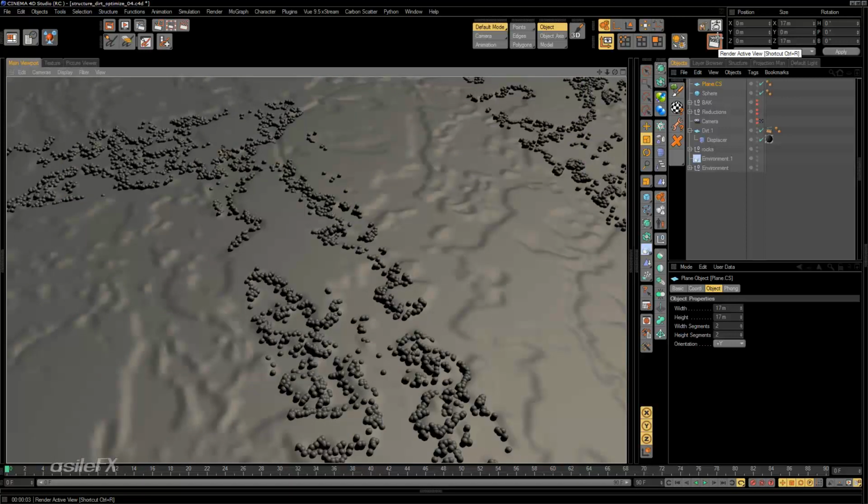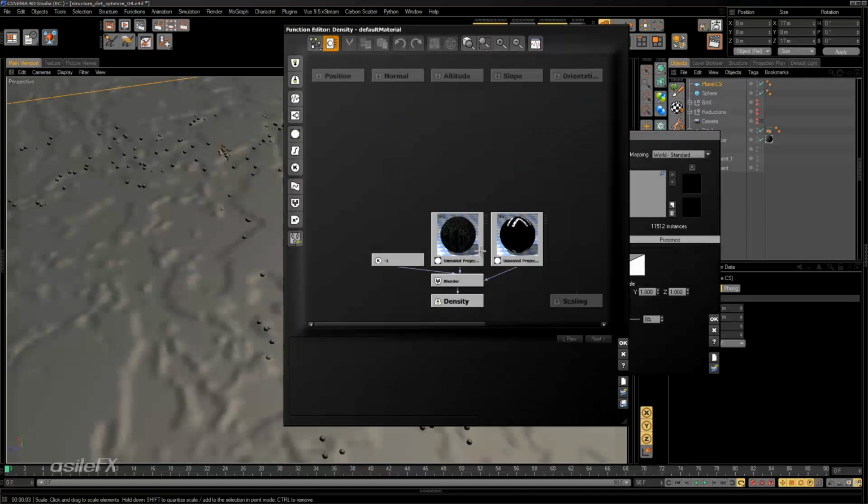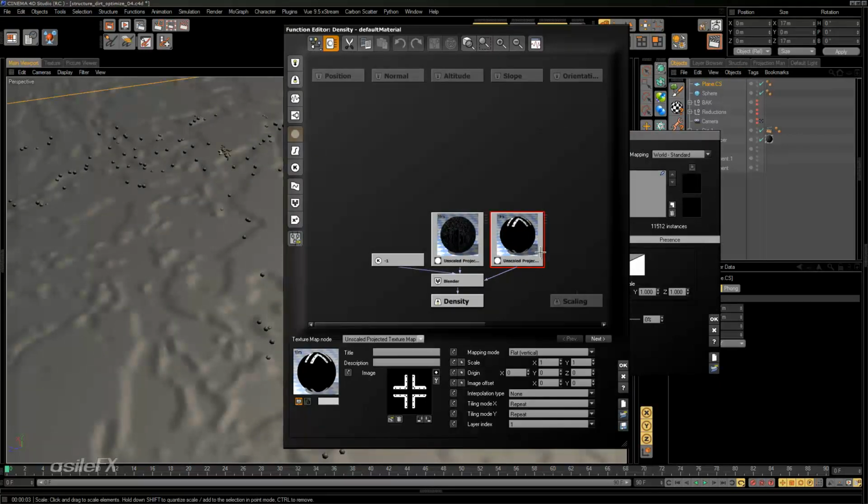If we want to, say, reverse this, what we can do is just a very quick change using the unscaled projected texture map that's controlling the ratio. There's a little button here above the Y. The Y is to control the gamma. I believe the system gamma might be set to 1.8. You can override it if needed. This isn't grayscale, so it shouldn't be a problem.